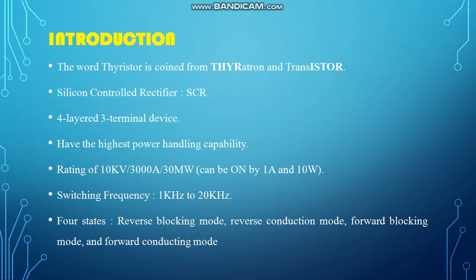It has a switching frequency from 1 kilohertz to around 20 kilohertz, and it has four modes of conduction or blocking, whatever. It has four states, I can say. First is the reverse blocking mode, then reverse conduction mode, then forward blocking mode, and forward conduction mode. Actually, in some books they have given only three states, that is reverse blocking mode, forward blocking mode, and forward conduction mode, because reverse conduction is not recommended.